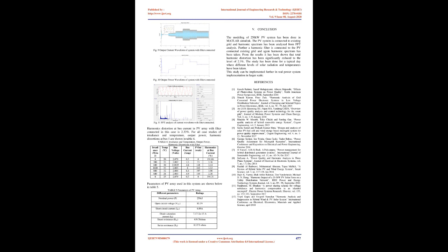We assume that in the last case, from morning 6 am to evening 6 pm, time equals 0, 1.5, 3, 4.5, 6, 7.5, 10 sec, irradiance equals 0, 0.3, 0.6, 1, 0.8, 0.6, 0 times 1000 W/m2, temperature equals 20, 25, 30, 35, 32, 28, 25 °C, and harmonic distortion is around 2.33%.